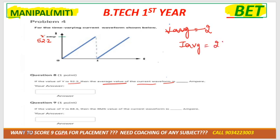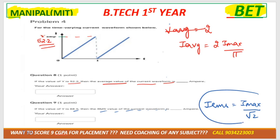I average is how much? 2 I max divided by pi. I max is how much? That is 52.2. Okay. If the value of y is this, then the RMS value of the current is, so I RMS is how much? That is I max by root 2. So you can get the answer.